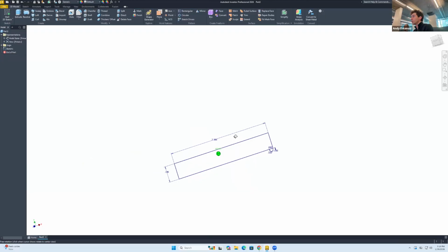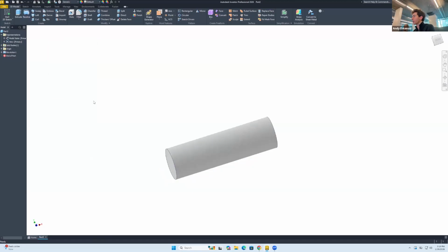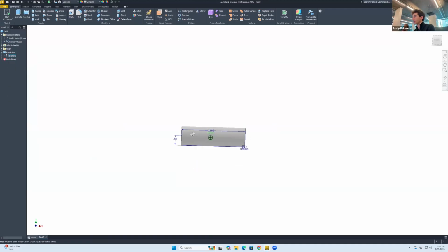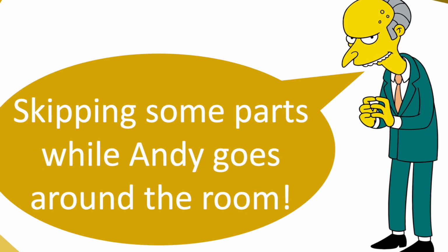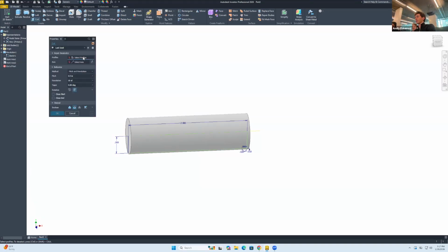Now, what we can do is go here to our friend the revolve, and we'll select this area and that axis. I'll say okay. Now everything disappears, so probably we will have to bring this sketch in here, visibility. And then what we're gonna do is I'm gonna create an axis in here. And now what we're gonna do is this command that's called coil. So for coil, it will ask us for a profile.